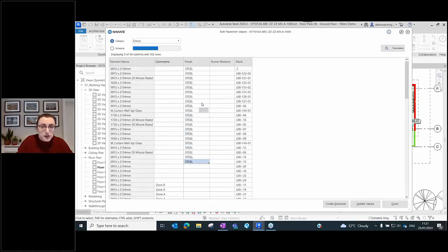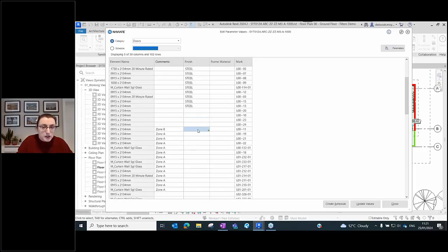So what this allows you to do, rather than copy and paste between each row, which you would do in a Revit schedule, is I use this green plus symbol at the end of the row, and I can drag that down, and that will give me the option to fill copy, which will copy and paste all that information. Or if this was a number sequence, fill increments. So if I was doing my sheet numbers, which I'll demonstrate shortly, it will increase everything in sequence for me as well.